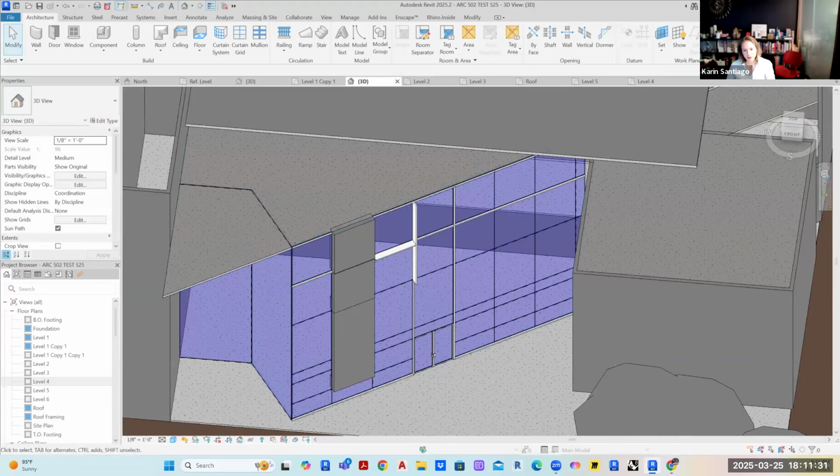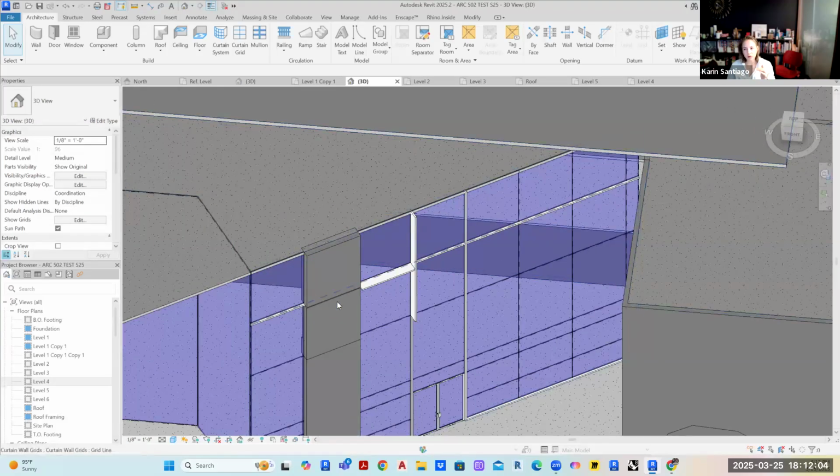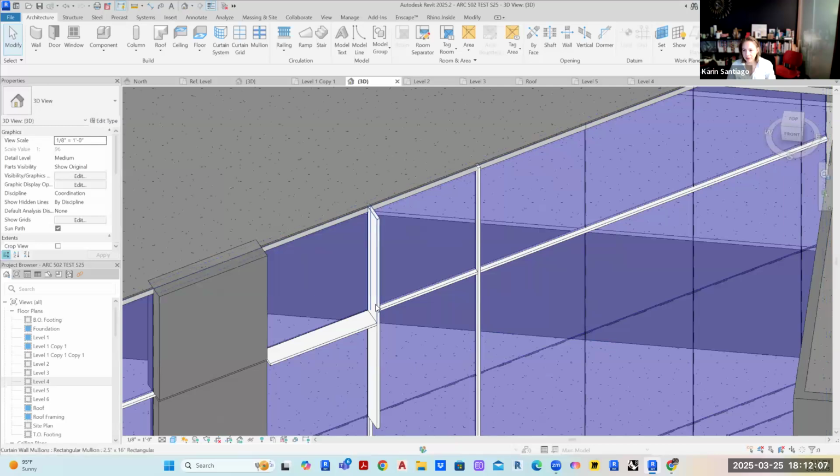You can spend maybe an hour or so in a section of curtain wall until you get it just right. I tend to think that the best approach is to find ways to, if you can, bring some opacity to your walls, especially on those east and west elevations. If it's warranted, make sure that there is some opacity. And on the south elevation, I would probably be looking at making more of a horizontal with my mullions.